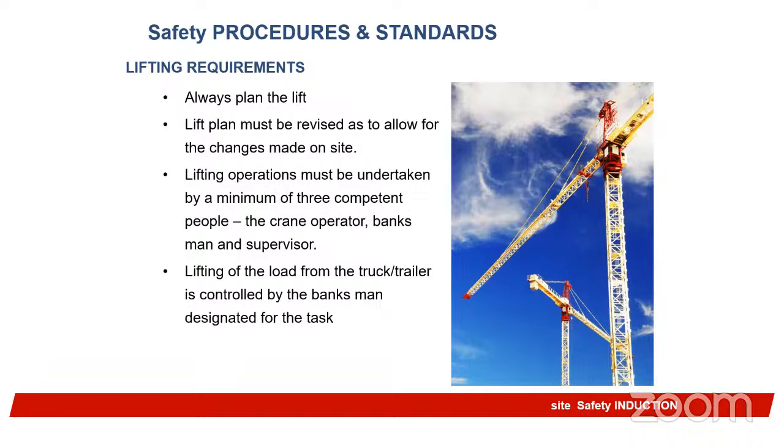Lifting operations must be undertaken by a minimum of 3 competent persons. That is very basic: the crane operator, the banksman, and the supervisor. Lifting of the load from the truck trailer is controlled by the banksman designated for the task. The banksman must be there at all times to coordinate.